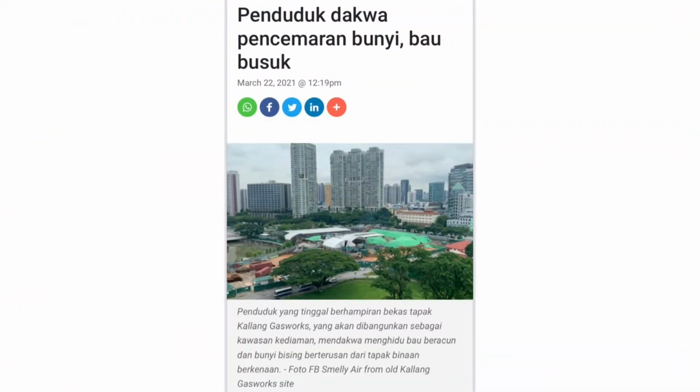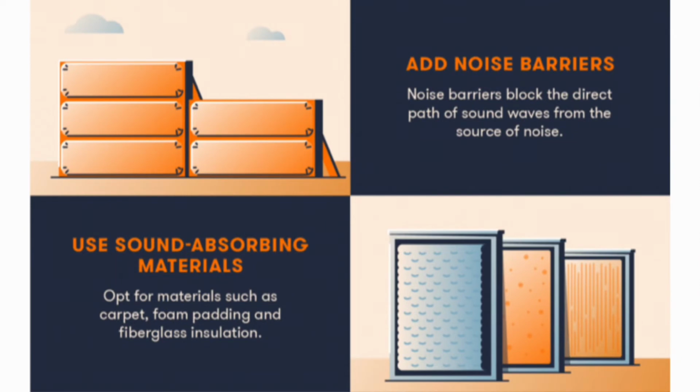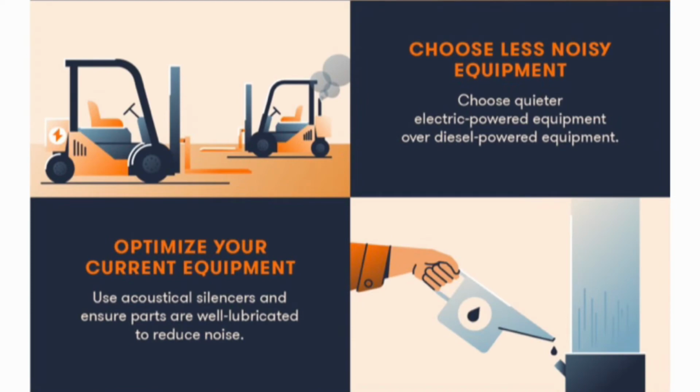The next solution to overcome negative impact is by using a noise barrier. Construction noise is a significant cause of pollution. The majority of the noise comes from machinery used for site preparation, demolition and landscaping. The main preventative techniques for reducing noise pollution are using moving noise barriers, erecting wall-like structures to act as sound shields, carefully handling materials and using quiet power tools and equipment.